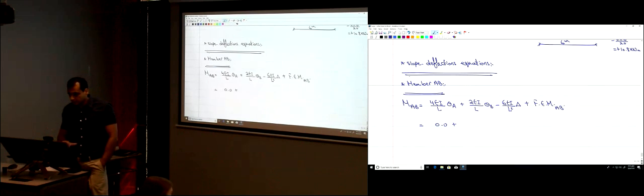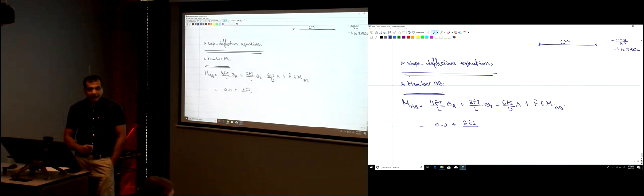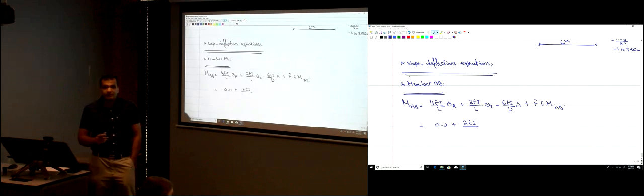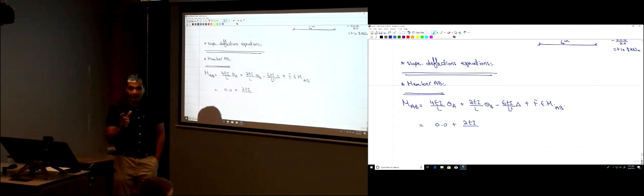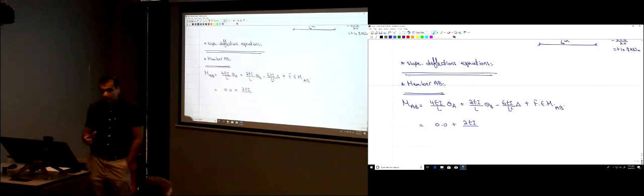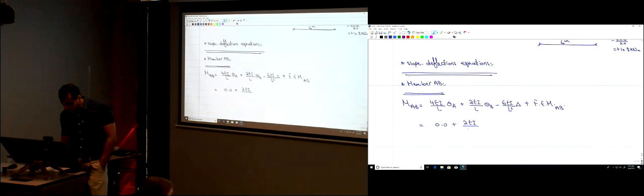It's just a constant, right? In the problem it was given as a constant, 2EI divided by L. How much is L? Not 6. I'm applying it on member AB, so L is the length of member AB. Okay? I'm studying member AB, so this is 8 meters.